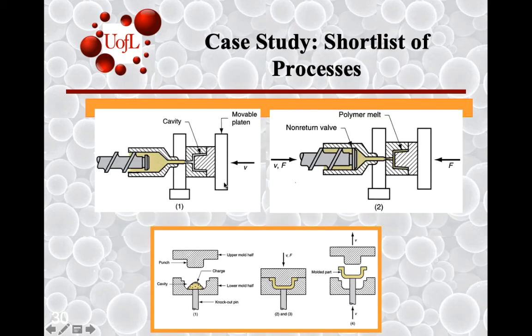And the top half looks at some variations in terms of what is required for the die design relative to the part design and the injection molding conditions for being able to make defect-free parts, high-yield parts, and how to address cost-related issues between this option over here or go to a compression molding variation depending upon the chemistry and the shape-related attributes.